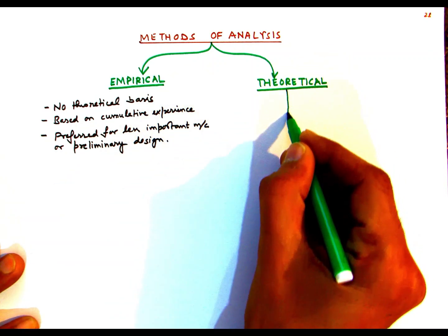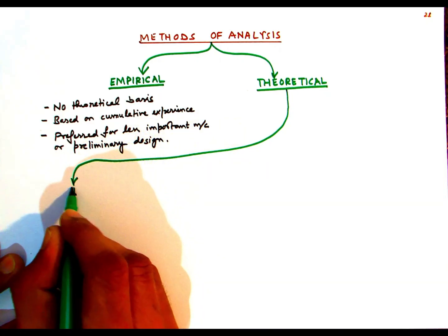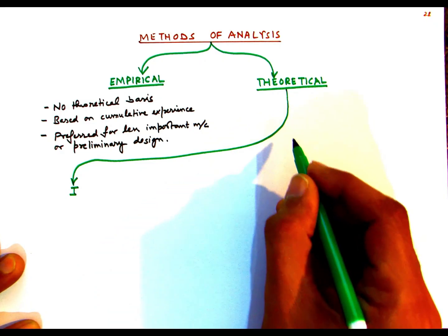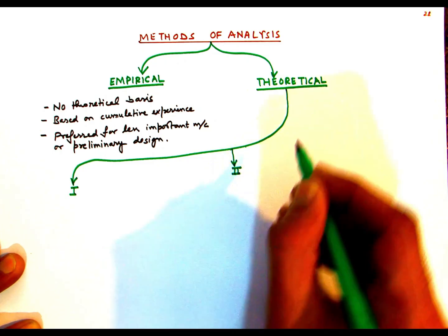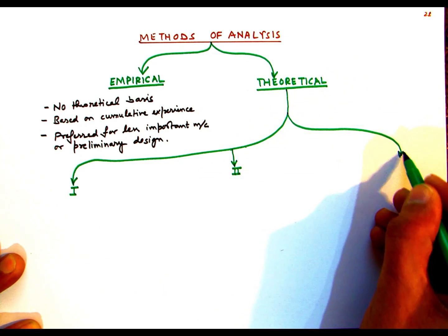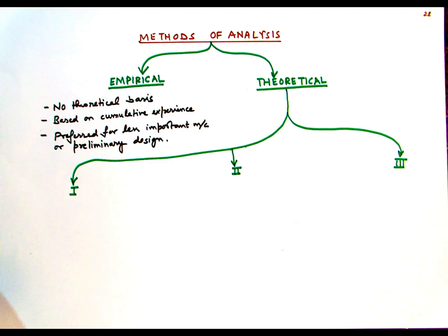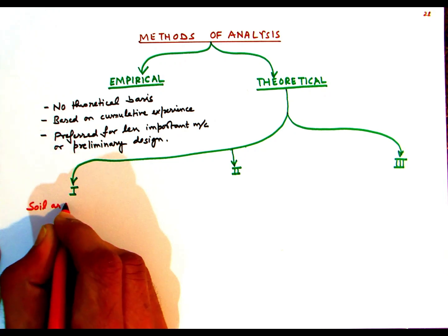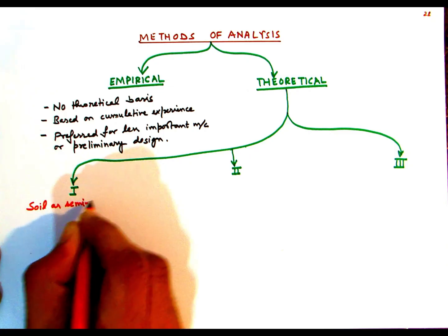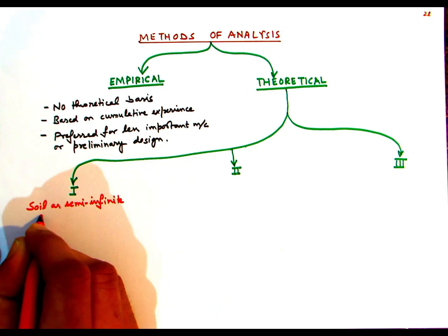The theoretical methods for analysis of block type machine foundations can be classified into 3 categories. The first category of theoretical methods are based on modeling the soil underlying the machine foundation block as a semi-infinite elastic medium.